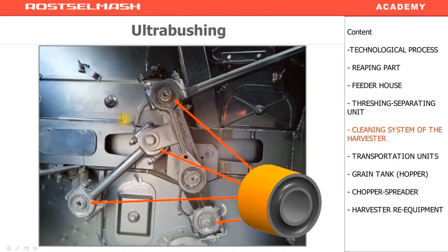Ultra bushings, which are installed on the levers, are press-fitted or removed with a special dismounting mechanism. Bushings replacement must be done with special care. If you have to replace the bushings, remove the old ones, insert the new ones, but before pressing the covers, put the lever in the neutral position.